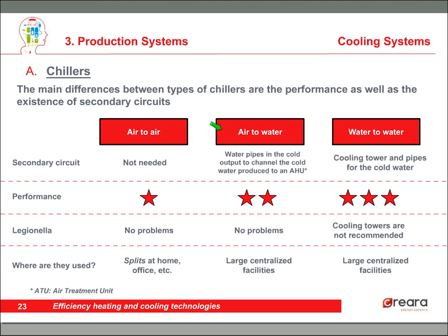The best performance is achieved by the water-to-water systems. And the problem of the water-to-water systems is Legionella. Cooling towers are easily affected by Legionella if they don't have good preventive and corrective maintenance.